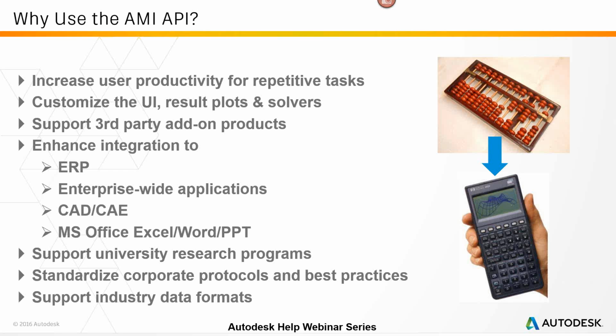And again, as I said before, there is the ability in the 2016 release now to actually modify the viscosity model that's used. So if you have a special viscosity model that you want to utilize with a particular material, you can actually go in and modify that currently in the software that you have right now. We do support third-party add-on products. It does enhance integration to things like ERP systems, CAD/CAM, Microsoft Office. You can integrate it with Excel, Word, PowerPoint, and you'll see some of those examples today.